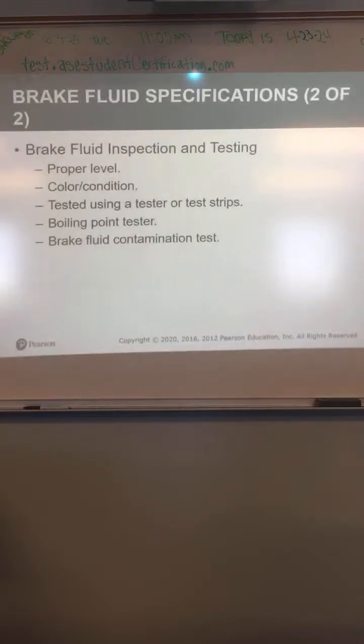Okay. Inspection and testing of brake fluid. They do make test strips. I don't know if the shops have them, some do, some don't. Normally, you would just look at the color and the level, right? Is it between the minimum and the maximum, and does it look okay? If it's dark, obviously it should have been flushed a long time ago, okay? It should be clear to amber in color.